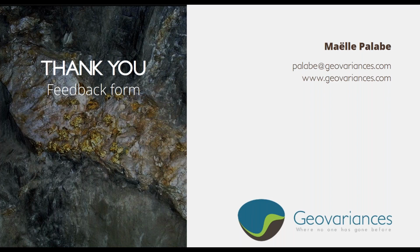Yes. Okay, so we have a question from Eduardo Takafuji, who asks, can we use capping on the log values? Maybe a log transformation would help define the gaps in the distribution. Not directly in the grade capping interface itself, but there is a calculator tool in Isatis Neo that allows you to take a log of any variable that you want, and you could then apply capping on those and find your appropriate cutoff in log space, and then unlog the data afterwards manually.